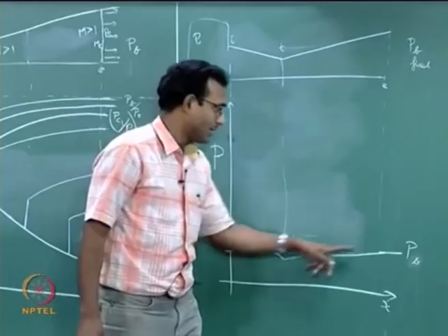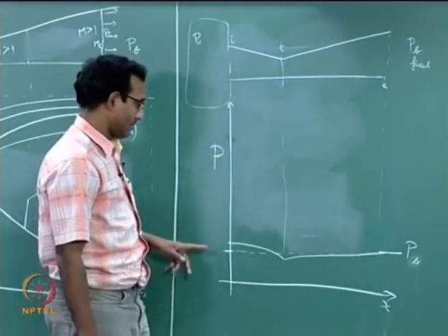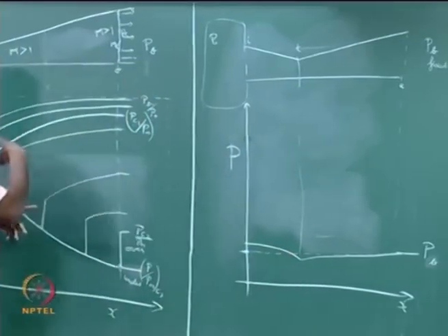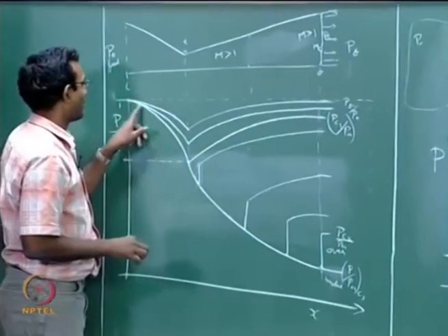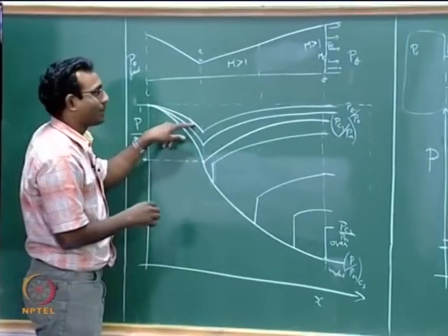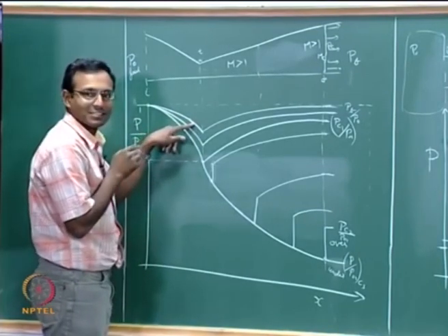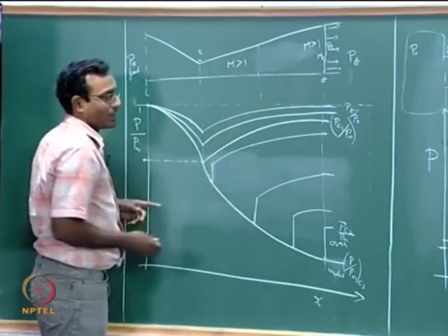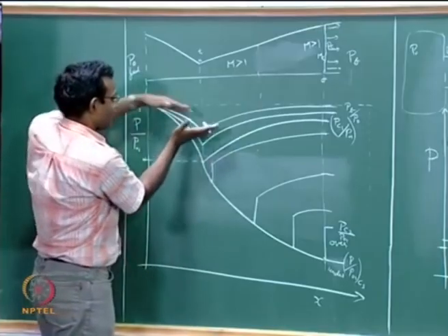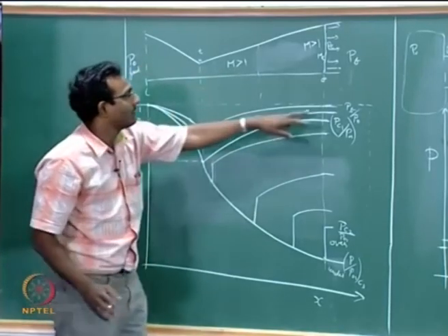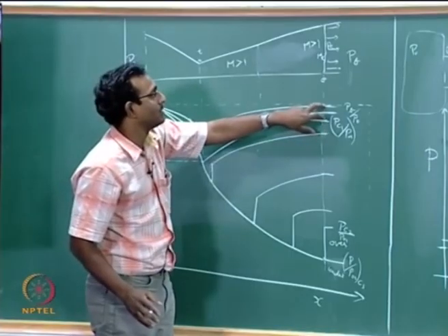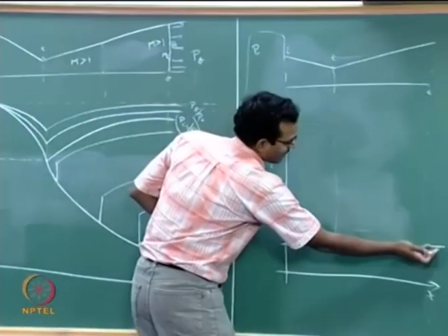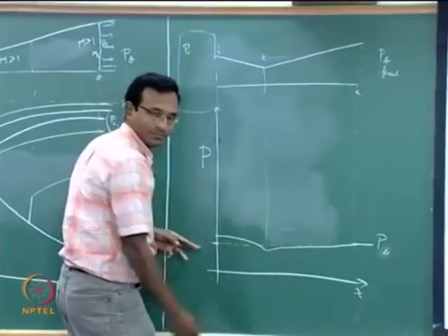It will go below and above, right. So, if I think about it like this, what have I done from the previous plot? Let us say it was this particular curve, let us pick. Say I had that particular Pb divided by P naught as the other curve there. What I have done is, I have multiplied this curve by a P naught such that this curve has been scaled up a little bit, and this point has been made to reach this dotted line. Okay, because Pb is a particular value, we are fixing Pb. So, it has been made to reach this dotted line, that is all I have done, it just came here.